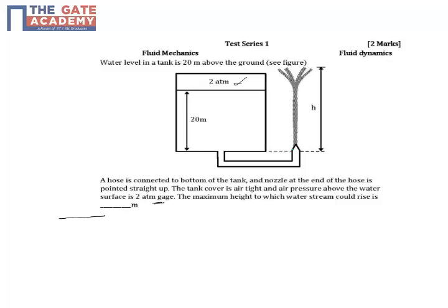At the end, you have a nozzle where the water will be coming out at a very high speed, and so when you keep the top end like this, the velocity will not end immediately. Somewhere at the top, the water level will rise up to a certain height, so at that point the velocity will be zero.